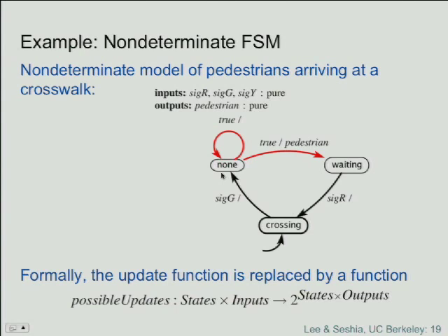We would take this state machine, compose it with the traffic light state machine, and we would declare a safety condition. A safety condition might be something like, if a pedestrian pushes the button, this would be a liveness condition. If a pedestrian pushes the button, the light will eventually turn red. Okay? That's a condition that we could explicitly give as a mathematical formula. And then we could show that this composition of state machines does not satisfy that condition. And moreover, we can algorithmically find the counterexample that shows what are the steps that led to that pedestrian pushing the button and the light not turning red.